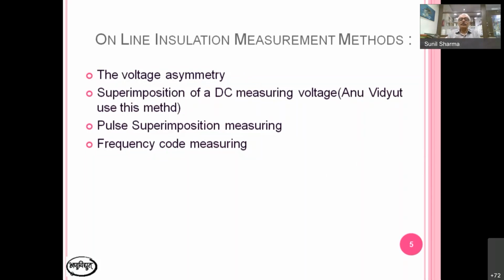If the voltage is the same, they assume IR is okay. If there is a big difference, then they assume that one side IR is low. This is an approximation method actually, but it also works. No doubt, when they have no instrument, they do it like that.